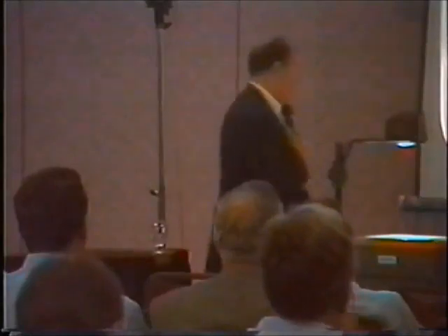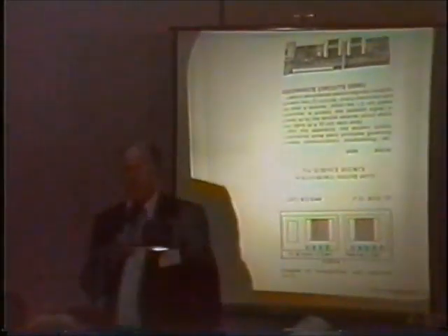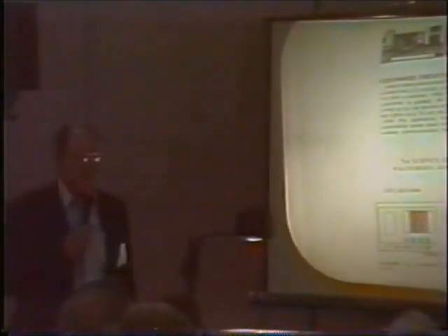Well, there's a capacitor in there. It's a small capacitor. Actually, you can see there's a butterfly tuning capacitor there that's like 250 microfarads, or rather picofarads, 250 picofarads, which would get you into the AM radio frequency with that particular coil winding.